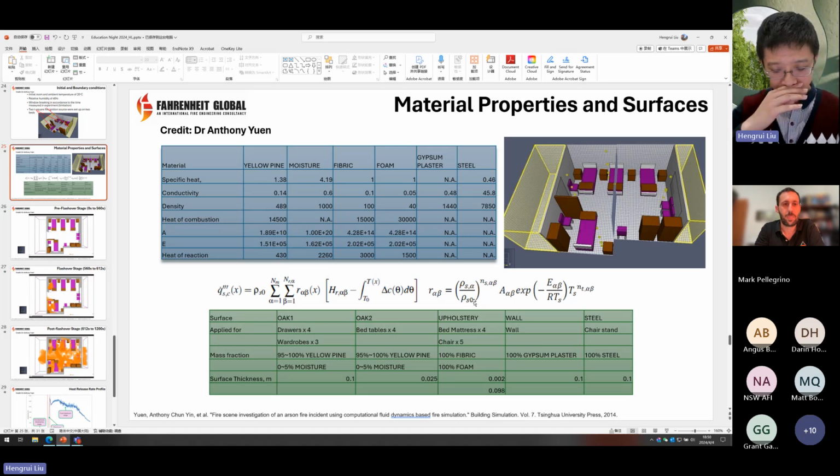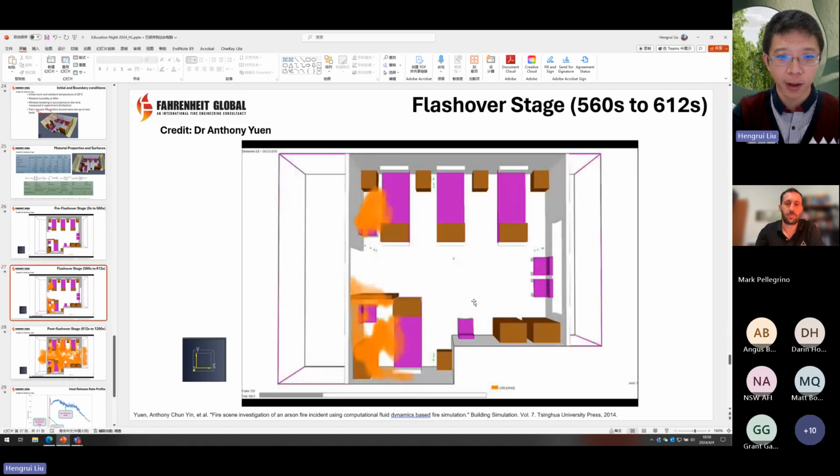And as well, battery fires behave very differently compared to a normal fire. Battery fires are often jet fires, because the gas only leaks from a small crack or a long crack at the edge of the battery, and it will lead to a fire plume or a fire jet. We don't really know where the fire jet starts either, because we don't know where it will crack. So that's somewhat of the challenges that we face for battery fire as well.